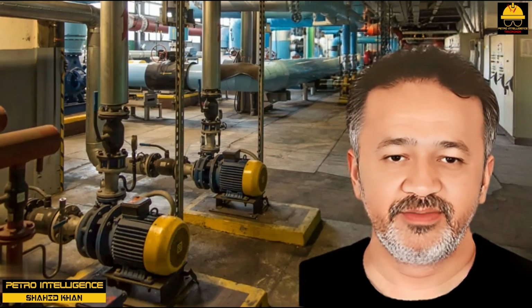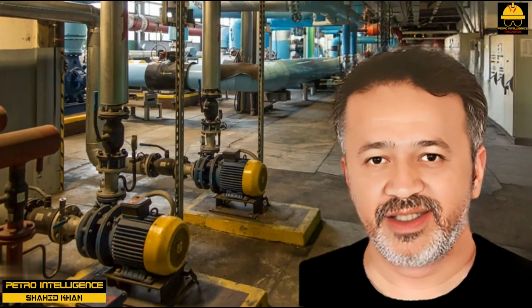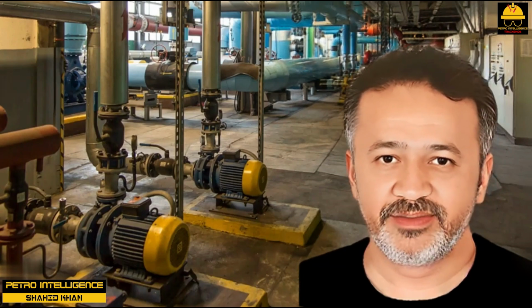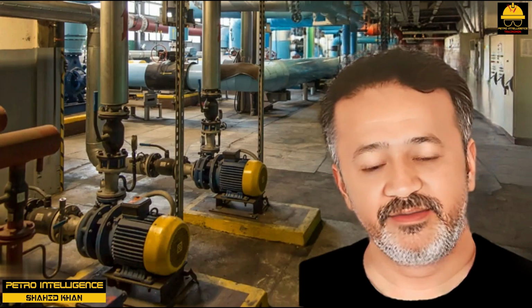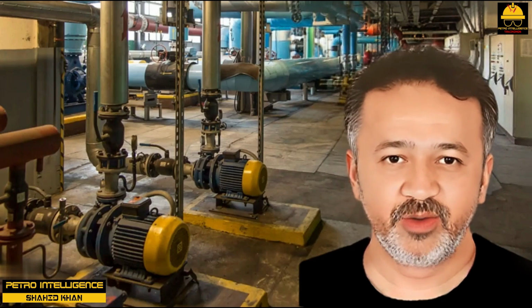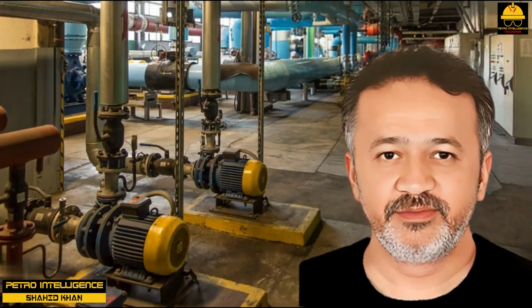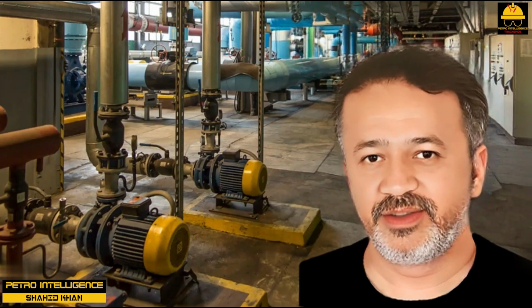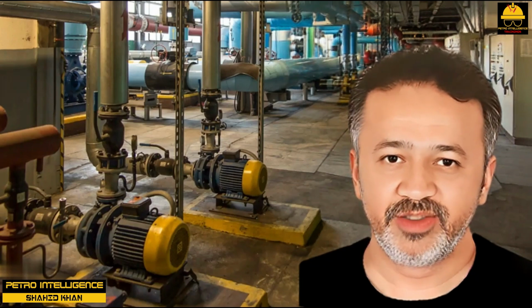Thermal protection. I made the statement earlier in this lecture that alternating current motors operate at a constant speed. I said this because I read it in a book. Yet I know from personal experience that this is wrong. I know that my wood turning lathe will slow down if I press too hard on the spinning wood with my cutting chisel. The lathe is run by a 1750 RPM, 60 Hz, 120 V, 3/4 horsepower AC motor.